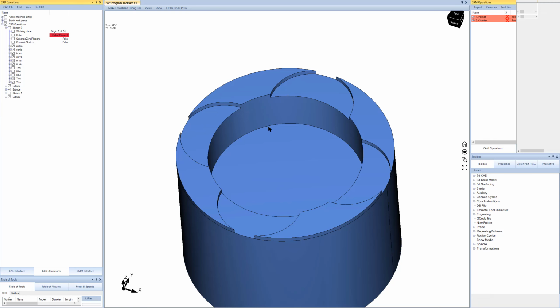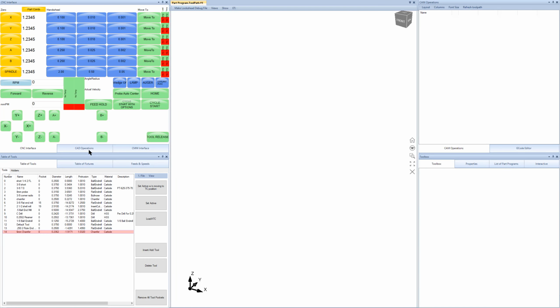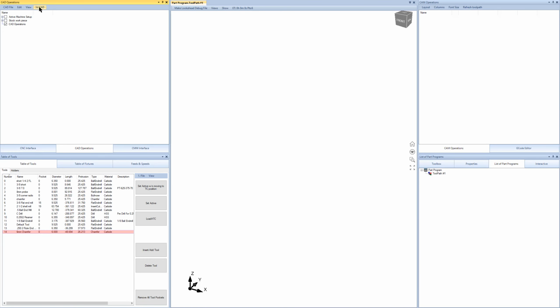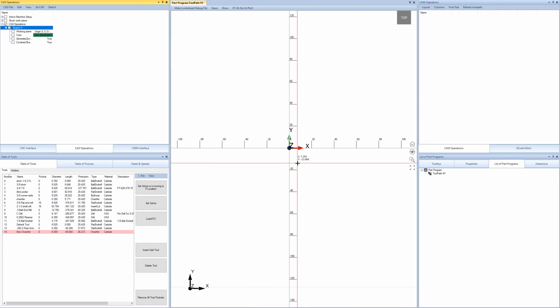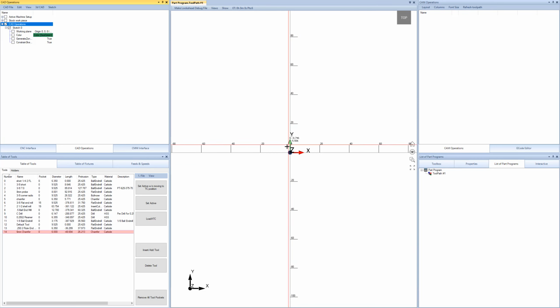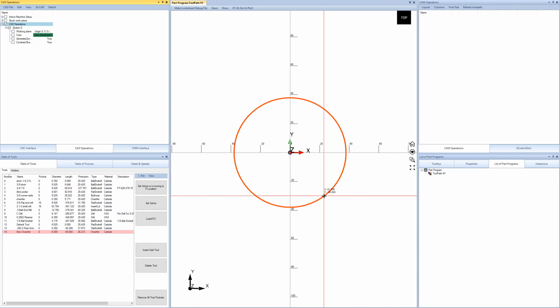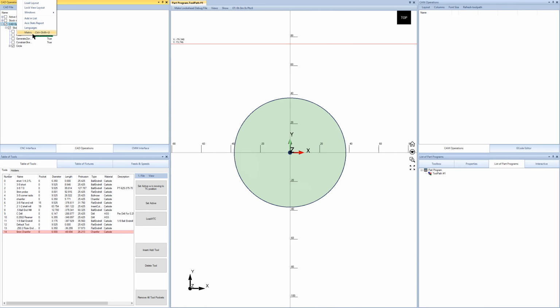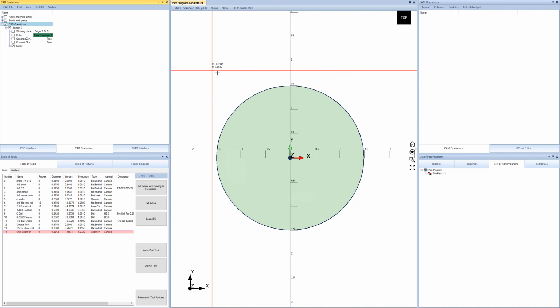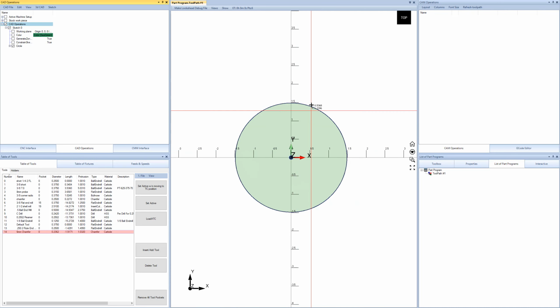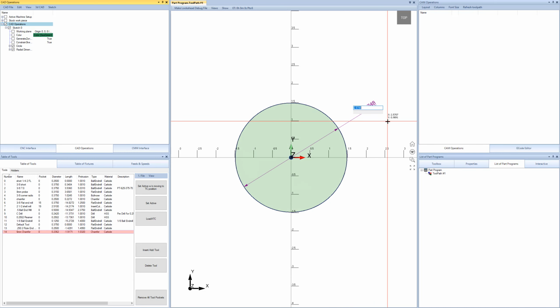Let's go to File and New and make a brand new program. The first thing I'm going to do is click New Sketch, and let's show our ruler, okay? Then I'll hit C on the keyboard for circle, and we'll make a circle. I think this is more commonly done in inch, so I'm going to change over to inch. Now I hit D for dimension, click on that circle, and put a dimension in here. We'll do 4 inches.